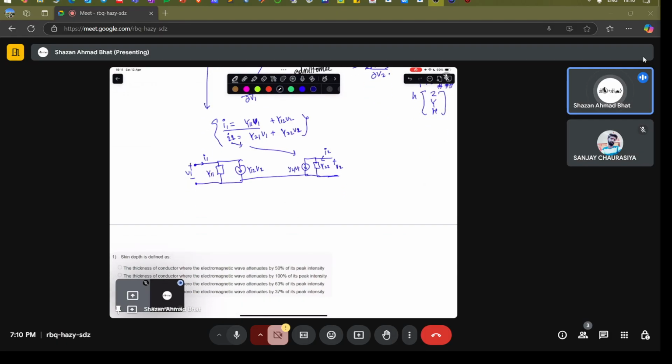And if you want to relate it to the transistor, the FET: this is source, this is drain, this is dielectric, and this is gate. If this is grounded, you have applied certain potential here, and certain gate voltage here, and if the channel is formed, the electron will go in this direction, and the current will flow in the opposite direction. This is drain current ID. This particular current basically is ID, which is gm times VGS.